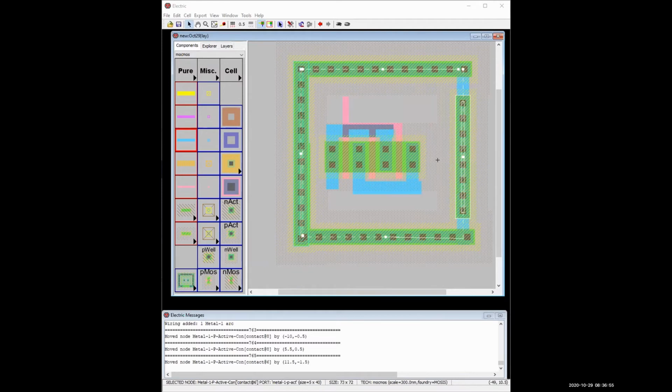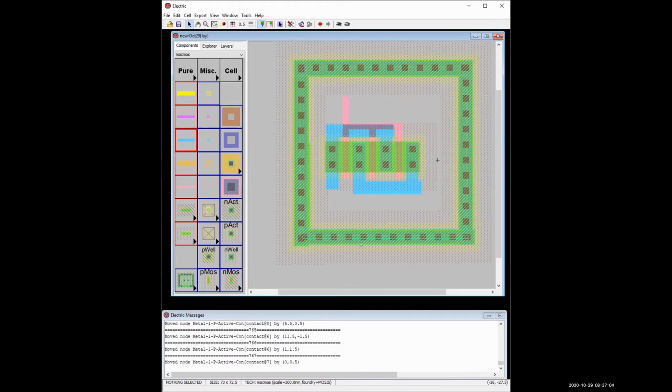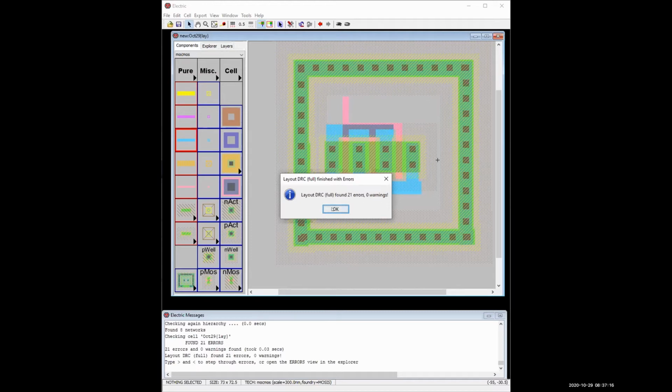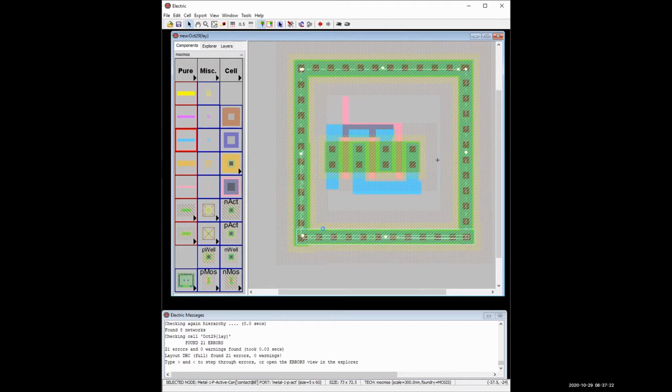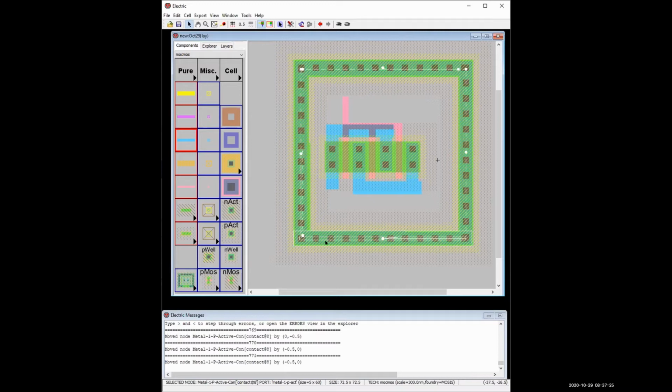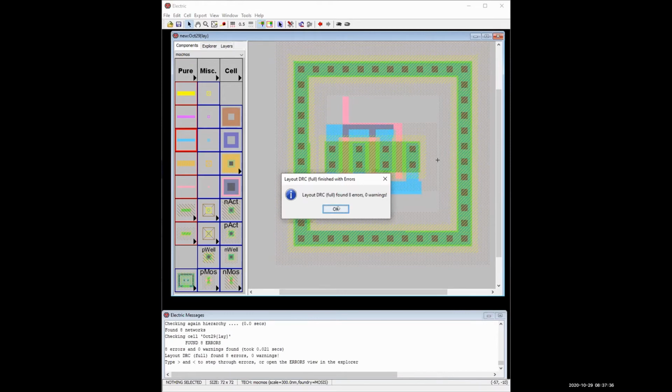So if I do this, you think I would be okay? If you were. You see how you're going to get at least 4 errors just based on the size of your contacts. Okay. So take your bottom piece, that guy right there, and move it down 1 and to the left 2. All right, take that guy, move it down. Now press F5. Only 8. That's pretty good.